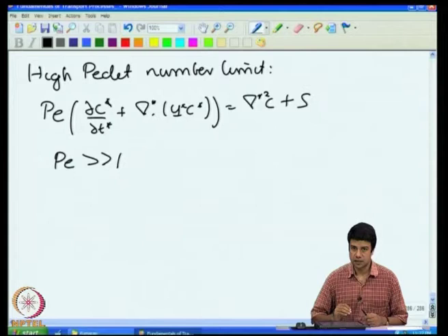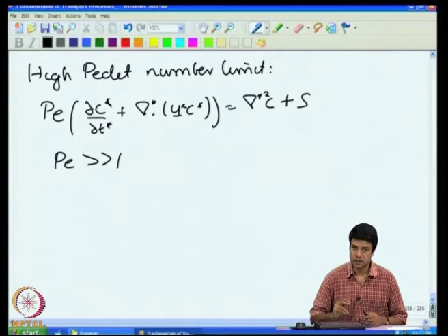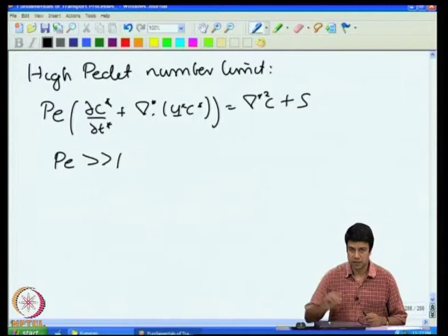The physical reason for the inconsistency is that convective transport only takes place along the flow, diffusion takes place in all directions equally. At a surface, there is no flow perpendicular to the surface. So, one cannot have convection perpendicular to the surface itself. At the surface itself, ultimately transport has to take place due to diffusion, due to the fluctuating motion of the molecules. If the velocity is large, the convective effect is large, there is still diffusion taking place from the surface, but it will penetrate not very far because it is being swept backwards by the convection.